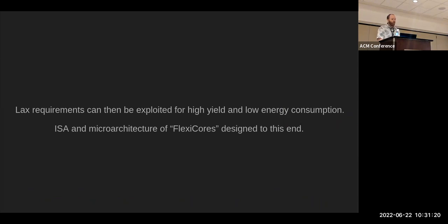Flexible application requirements can drive architecture and microarchitecture decisions that enable high yield while minimizing energy consumption. We appropriately designed the ISA and microarchitecture of our flexible processors. We call these processors FlexiCores. FlexiCores are designed to minimize gate count, leading to high yield and low power consumption.